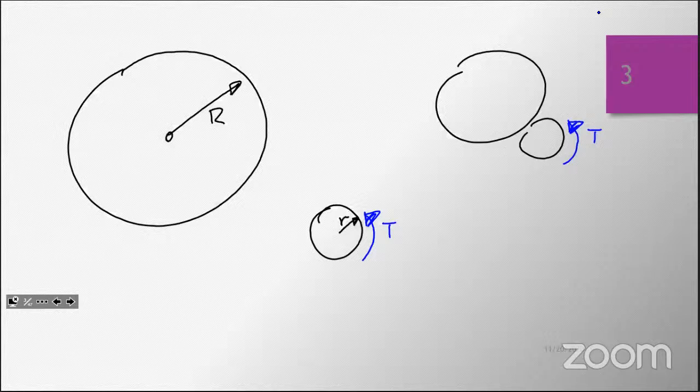If I'm drawing the free body diagram for these two, it doesn't matter which way I draw this. But where these are in contact, there's some contact force that I'll call F sub C. This is just the contact between the two gears. Also at that point, because the two gears are touching, they both have to have the same tangential velocity. If they didn't, that would be weird. They're in contact and they're moving. So at that moment, they both have the same tangential velocity. That's going to be key in a second.